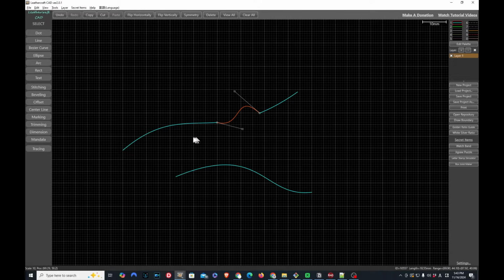In this case, this one, it also changed it. But from this version, it will only change when it's selected. So let me do it. Right now it's not selected, and I'm holding the Shift key and changing one of the control points. It doesn't do anything.